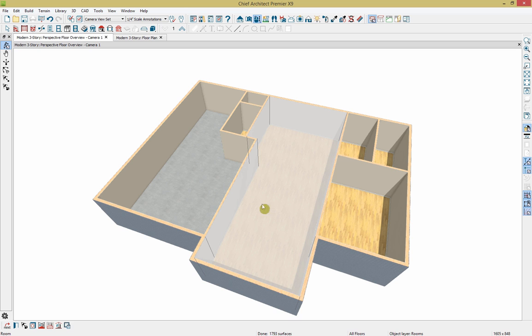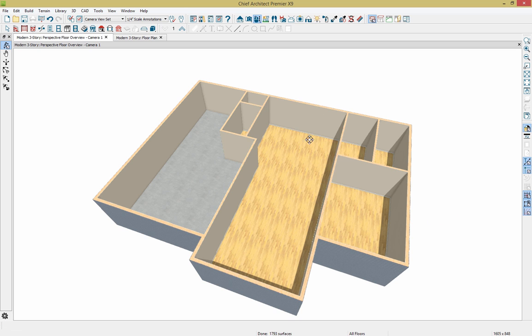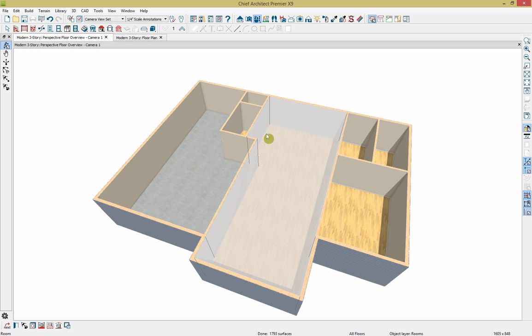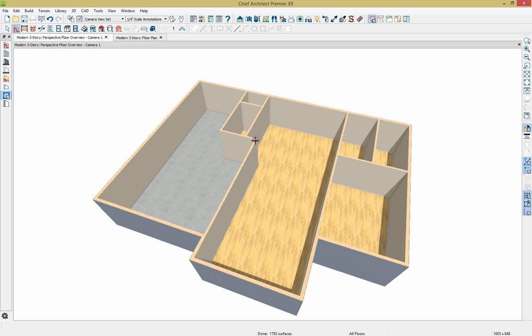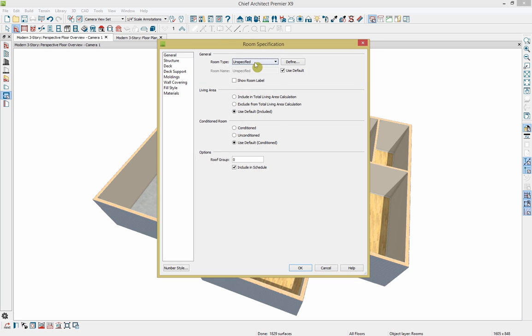And in this space, I'd like to put a kitchen in this back area, and I'd like to have tile there, but have it open to the rest of the space. So when I select it and want to modify, the entire space is selected. So what I can do is use my room divider tool and just click and drag out a room divider, and now I can single click in just that portion and I'll open up our kitchen, change the name, and then you can also rename that if you want to have something a little bit different.